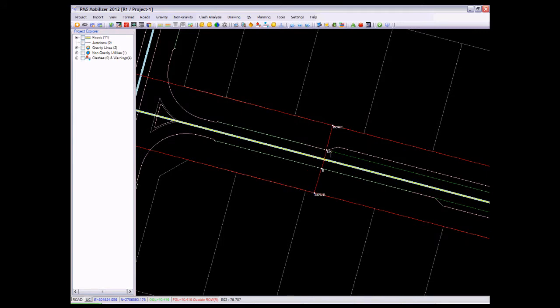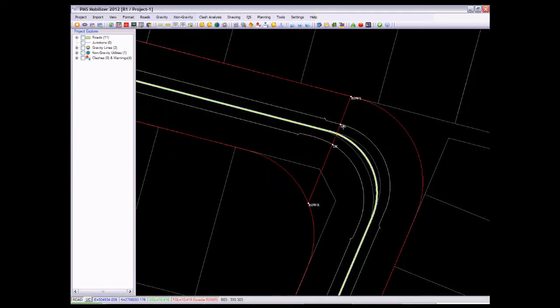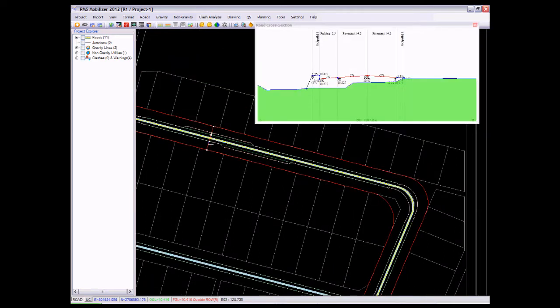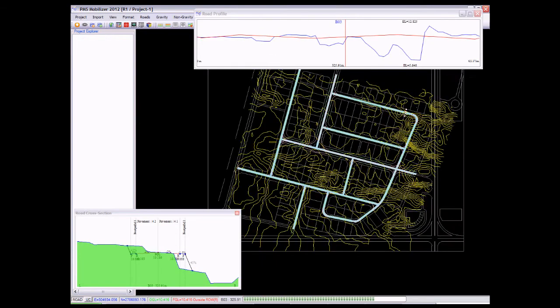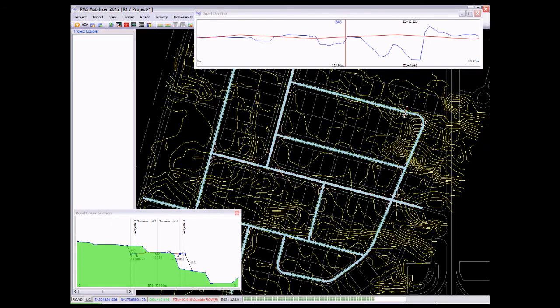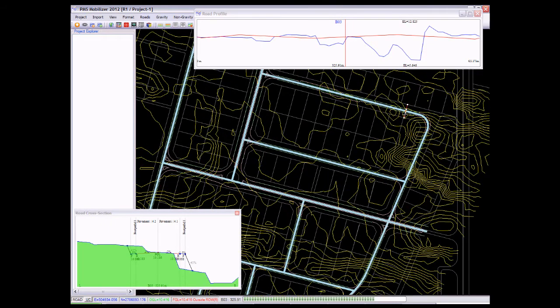Import road surface elements like curbstones, right-of-way limits, parking bays, medians, etc. This method generates the cross-section of the roads automatically from the layout drawings and allows you to model any complex sections easily. Embankment cut-fill configuration enables you to generate sections with cut-fill details. Now, the original ground surface and the design surface are ready for utilities installation.